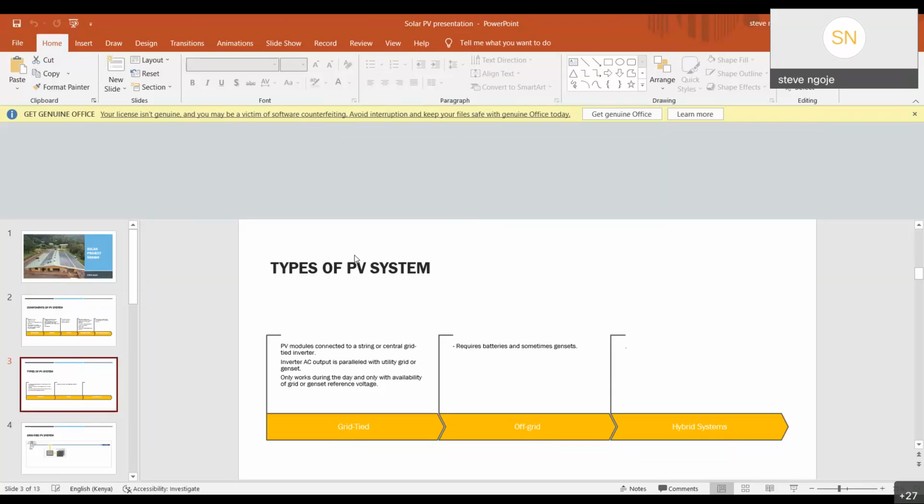If, for example, a cloud passes over your area, and now your inverter can only generate 50 kilowatts, the priority will be given to the inverter to give you the 50 kilowatts. Then the grid will bring in whatever balance is required. It's always going to be that type of trade-off. When one rises, the other goes down, depending on the environmental conditions that really affect solar generation.